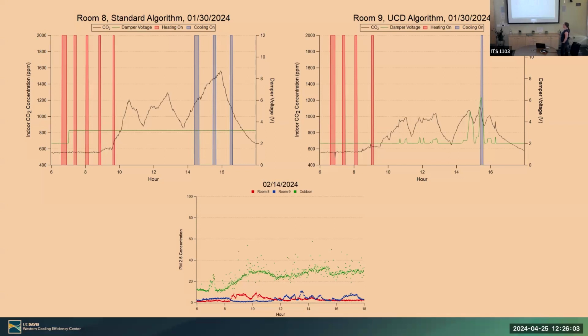Why didn't they economize in that? They must have disabled the economizer on this. And then the other question I had was, did this school already run their fan all the time? Because that's an issue, where they were running their fans all the time. You have to run your fans in commercial buildings all the time to be providing ventilation all the time. This essentially is case A in my simulations. This is just fixed rate ventilation. We're not using the economizer in the field study.